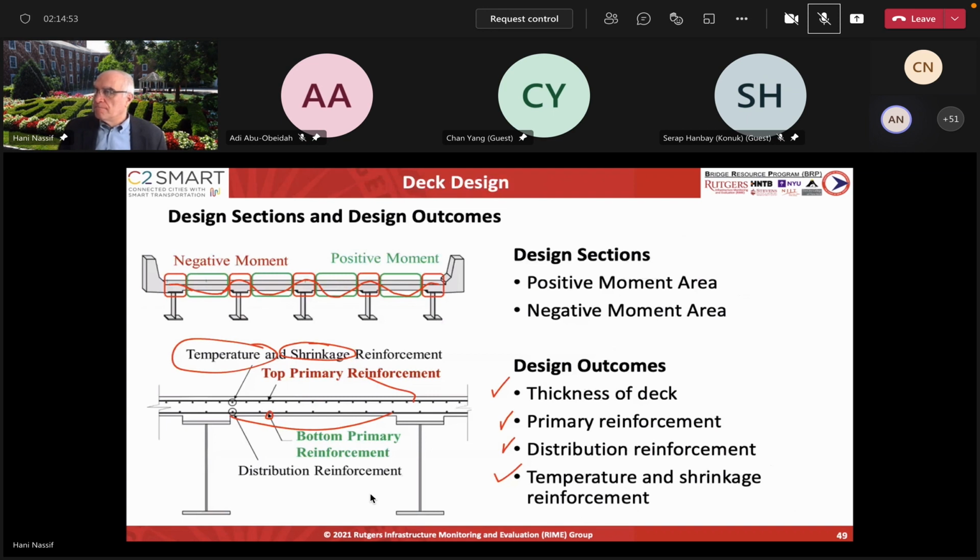just one thing, this one right here. When you are doing your traffic control staging, just make sure that when you're using those construction barriers, not to pin the construction barrier type C. Now we're going to have a type D with 0 deflection, not to put those pins on those negative moment areas. Because if the pin cuts any of those top mat, especially the transverse, you could compromise the deck. Right. So I just want to let our young designers know to keep that in mind, that when you're doing your traffic control staging, it's important to remember that